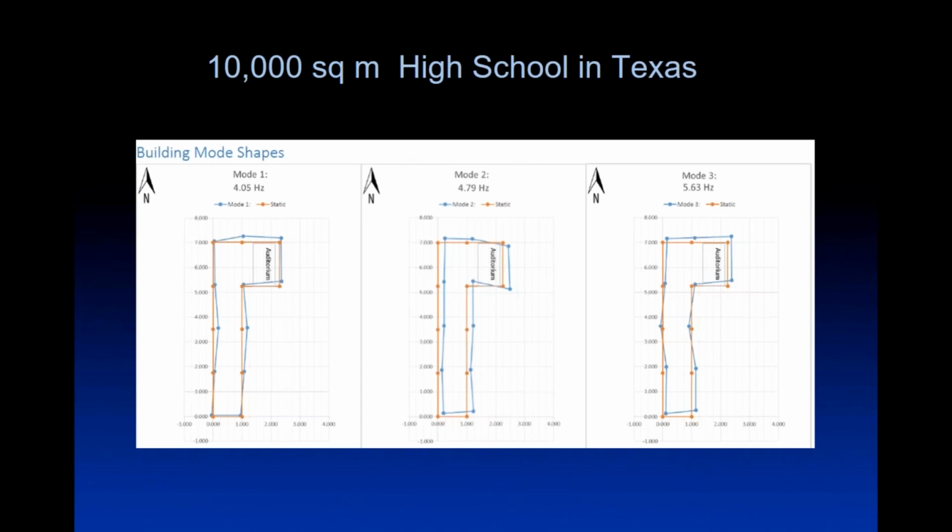Well, what we actually do is we'll make these measurements, and we'll take places where we're visualizing in our minds, if you like, what the dynamic characteristics are going to be. And we're looking specifically at east, west, and north, south, but then torsional effects as well. How often do we need to measure? And we're only doing that across the roof here. So we've got a number of positions, 2, 4, 6, 8, 10, 12 positions. That was all we needed. Each one of those took 20 minutes. The reference accelerometers stayed there for an entire day.